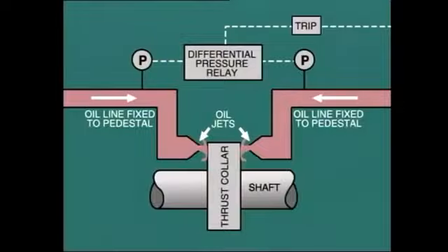This diaphragm works quite independently of the mechanical devices and hydraulic mechanism that we have been discussing. Usually, the only attention required is to make sure that the water seal around the edge of the diaphragm is not leaking and allowing air to enter the condenser. Another important protection device that is set to trip the turbine is the thrust-bearing failure monitor. This equipment is fitted to precisely measure the position of the thrust collar in relation to its pedestal. As long as the thrust bearing on either side of the collar is operating correctly, there will be no change in the relative position of the collar, even when the turbine shell and the turbine rotor expand.